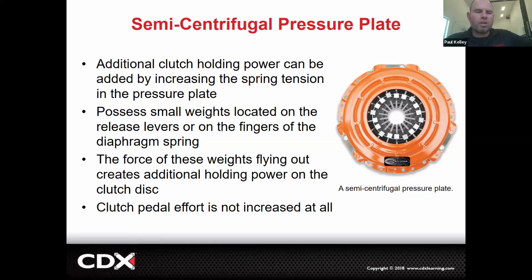So let's say it's any one of these performance cars from the factory. Let's say that you buy the regular Civic or the regular Corolla, they don't make a ton of power. Then you buy the Type R or the GR. They obviously make a lot more power. You'll probably need to increase your clamping force to have that clutch not slip, like my Civic, right? I put the horsepower to it and the clutch was like, I'm out. In Gen Z speak, the clutch left the chat. Okay. The clutch was cooked, these types of things.